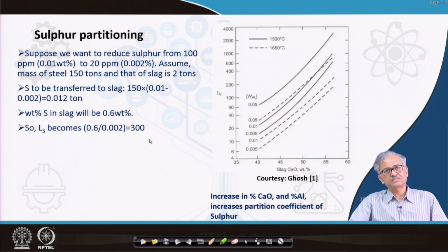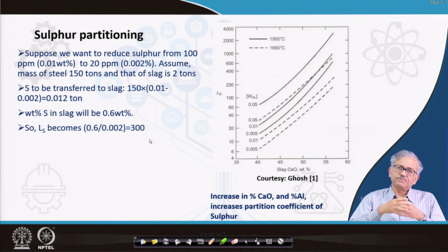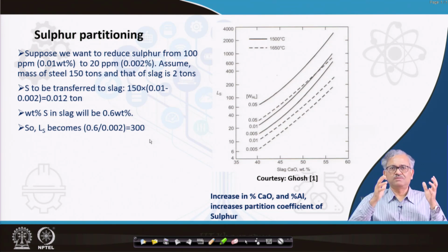Now you can understand that it is very difficult to attain equilibrium in steel making, in the ladle. Attaining equilibrium is quite impossible, but we still have gas stirring, where the fast mixing brings the ladle closer to equilibrium, though it stays further away because you cannot mix it completely. For that, it would have to be an ideal reactor like a CSTR, a continuous stirred tank reactor.